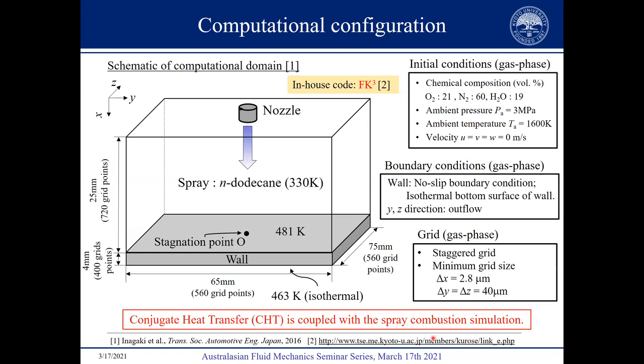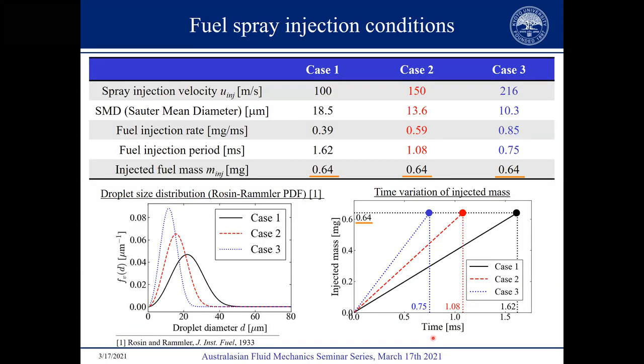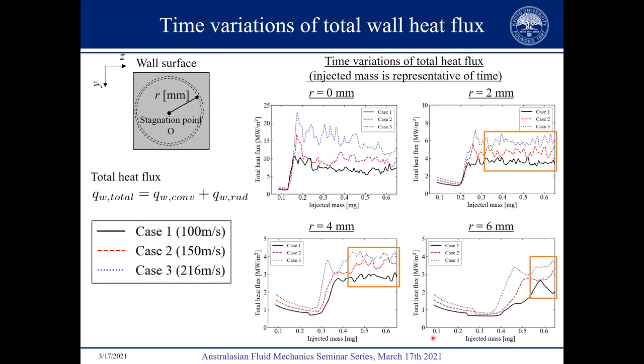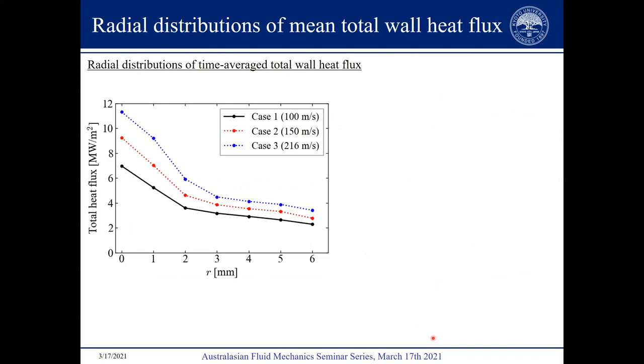Right. That's fine. And another point was, if you look at the heat transfer results, they're very similar to, let's say, a canonical case of a jet impinging on a heated surface. Exactly. But I think there are also studies where they have investigated an impinging jet on a moving wall, and what we see is that an oscillating wall will degrade the heat transfer rate. So this would be something, if your code can try to do that, because we have experimental data on a moving wall with the heated jet. If you can try to compare your simulations with that whenever that's possible, I think that would be a good benchmark. Yeah, definitely.